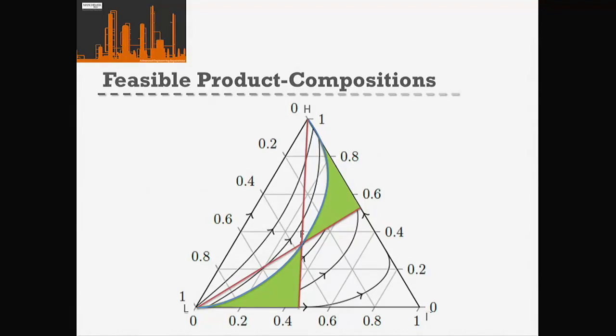Okay, so for instance, if we were to start at this point here with our distillate on this residue curve, so we know that our straight line must also end on this same curve, but must pass through that feed point. Okay, and that's physically impossible to do without drawing a curved straight line. And this essentially is our feasible region of distillate compositions, and this is our feasible region of bottom product compositions.